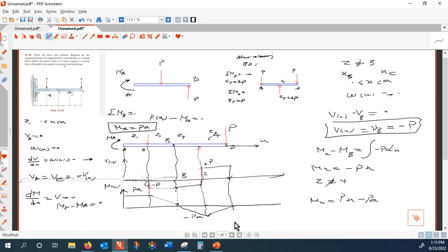And these are the variations of the shear force and bending moment. All we did was divide that composite beam into 4 zones. For each zone, we used the method of equations to derive V of x and M of x. Any questions? So the bending moment graph should always be equal to the shear force?